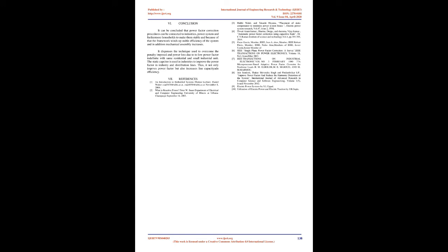Calibration process. A few factors are necessary to be determined based on the components used in the voltage and current sensor circuits. These factors are considered in the calculation of accurate power. Voltage and current calibration constants are determined based on the step-down and voltage divider ratios of PT and CT. kVAR calculation. The calculated power parameters are used in the determination of the required kVAR.